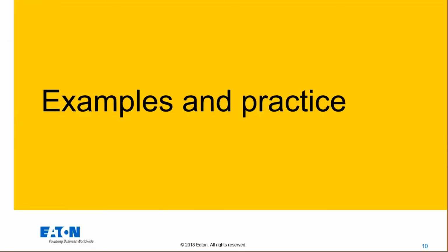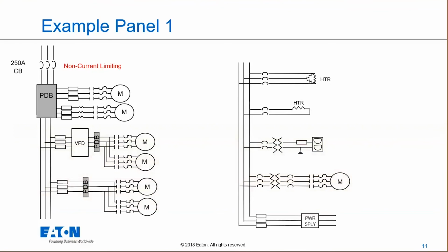All right, so now we're going to go through some examples, and these are just simplified. Excuse my drawings on here, because they're a little bit simplified, but I just want to make sure that it's clear as can be when we're looking at overcurrent devices, when we're looking at components, what their SCCR rating is. We've pretty much already gone through this little example here, and we went to the charts to look at what their SCCR ratings are. As we go through each branch on here, we're going to break this particular panel down to come up with an SCCR rating of this panel.